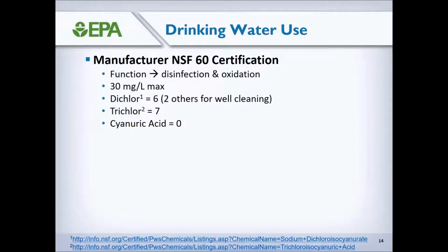In addition to the FIFRA registration, manufacturers have obtained NSF 60 certification for adding dichlor or trichlor to drinking water. This comes with a 30 milligram per liter maximum concentration, as approved under NSF 60. Six dichlor and seven trichlor manufacturers have received certifications for products, and they might have multiple products. But nobody has ever gotten certification for cyanuric acid proper for drinking water, even though they use it in the pool industry. Typically you find only dichlor and trichlor is how you add cyanurate